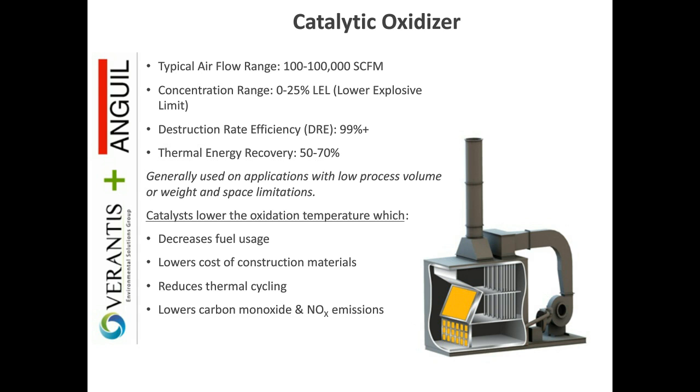In terms of LEL concentration, the same 0 to 25% applies as with the RTO. Now, the catalytic unit operates at a lower temperature due to the catalyst. We're operating at typically 600 degrees Fahrenheit rather than the 1,500 or so degrees Fahrenheit of the RTO. So you may think it's more energy efficient with lower fuel consumption.